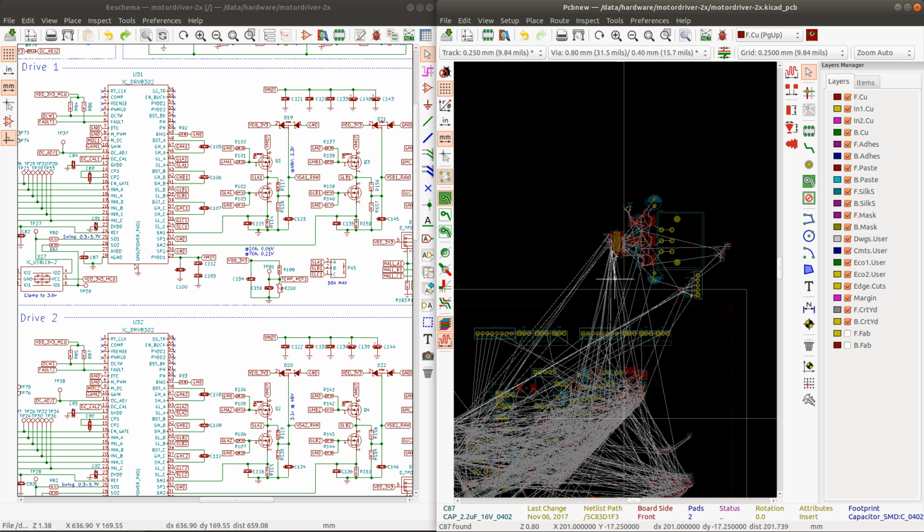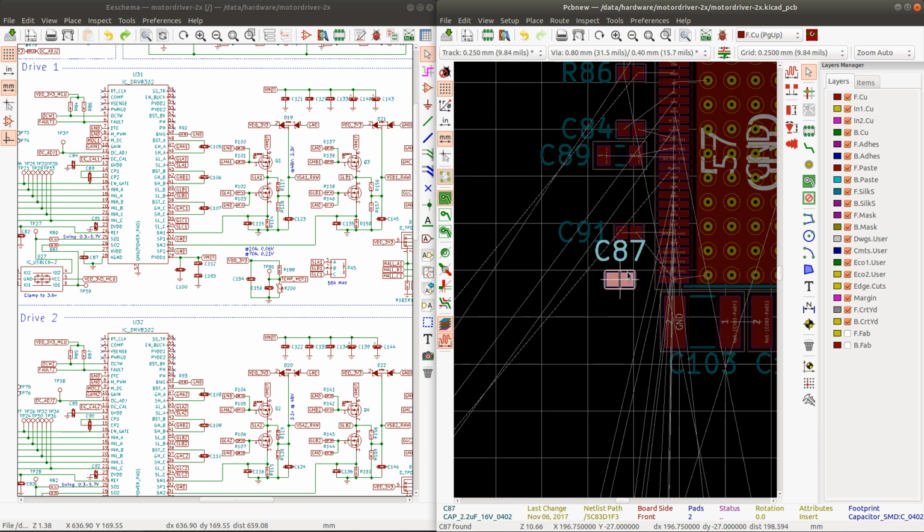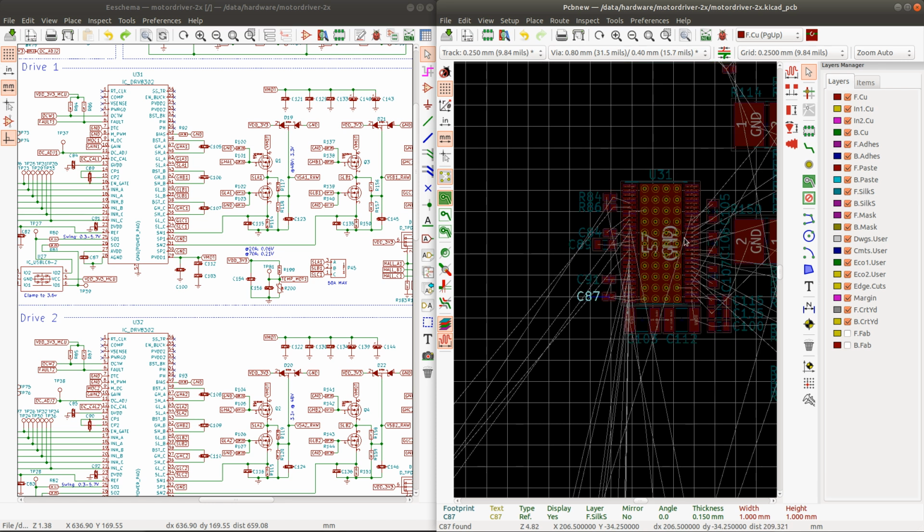There is a very good application note on minimizing electromagnetic interference from TI, which explains very well the function of the bypass capacitors. So the bypass capacitors are there to provide extra current. Whenever the circuit is switching, they provide extra current so that the current doesn't have to come from the power supply, which minimizes the noise on the power rails.